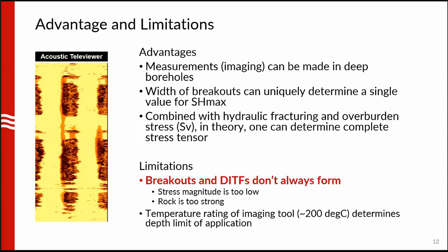So again, the advantage of this method is that you can apply this in boreholes, as long as you can image the borehole. So of course you can't go down 20 kilometers, but at least you can do this measurement at depth beyond what geotechnical methods can do. And then again, with the breakouts you can uniquely determine a single value for SHmax. Of course, discussions about error are always there, but in theory, you can do that. And if you combine it with hydraulic fracturing or density calculations, you can recover all three principal stresses.